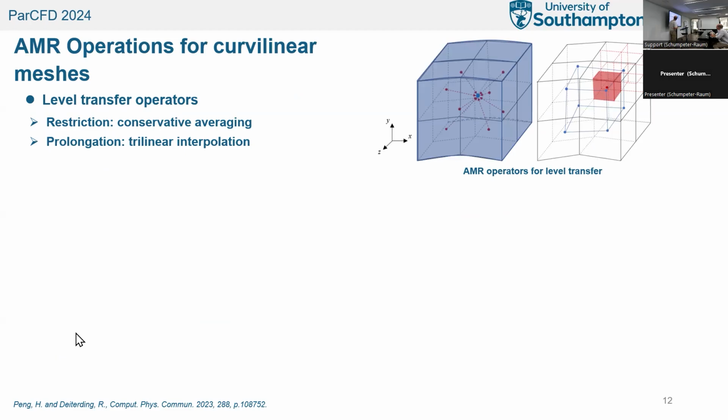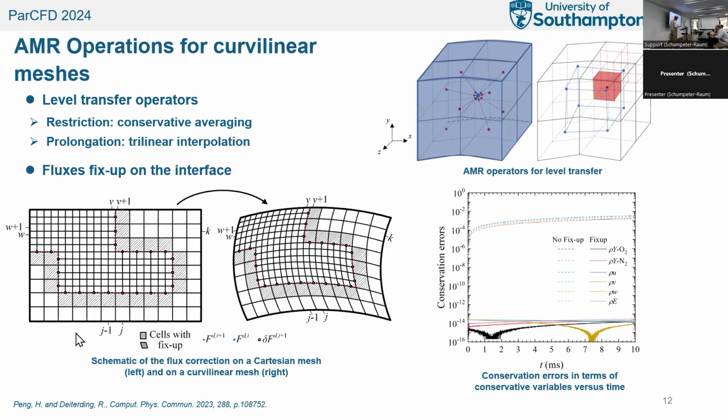In order to do adaptive mesh refinement on the mapped mesh, we can use all our Cartesian AMR machinery, because it works in IJK indices for the parallelization and for creating and handling the blocks. But of course, you need interpolation and restriction operations that consider the mapping.